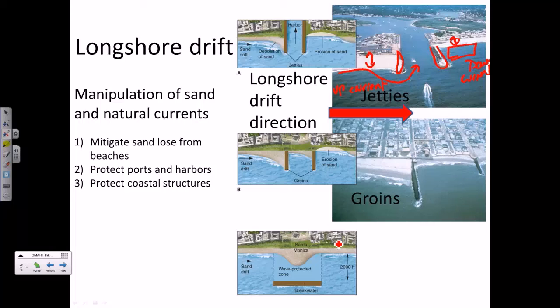We also do this kind of thing if we want to sort of stockpile sand in front of homes. And so we call these groins. Groins are very much similar to jetties. They come out and are perpendicular to the shoreline, but you'll notice up current of the groin, we find a thick beach, and down current we find a thin beach.